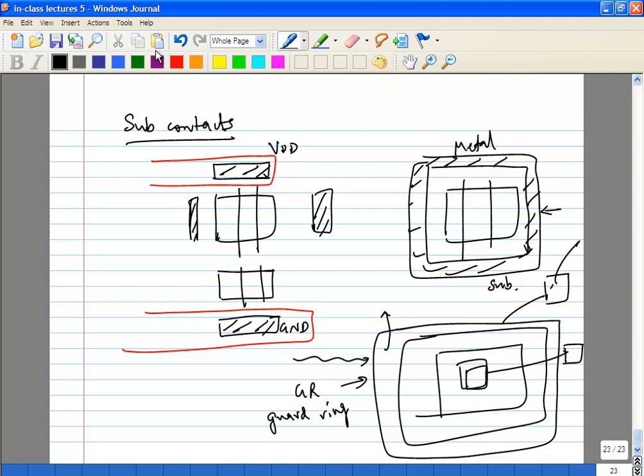So obviously at some point it's going to be connected up, but you keep increasing the impedances along this path until the point where the noise wants to split, right? So let us say it's coming here, at this point the noise wants to split, you're going to have a very good connection to ground on the PCB, let's say. So it is going to prefer to go there instead of coming back through this. That is the idea. Try to increase the impedances on the two paths.